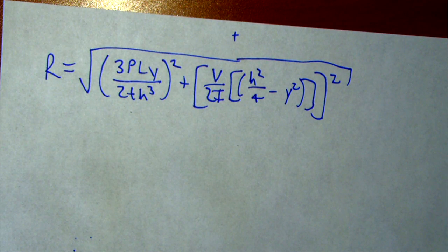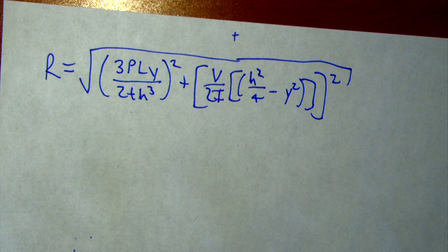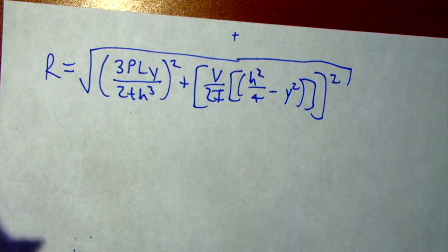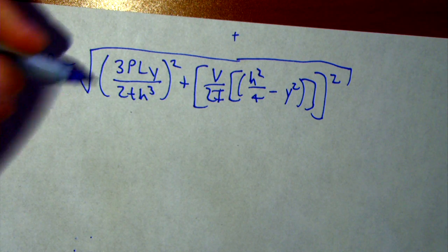So at this point you might say, what the crap, man? I thought we were going to get a Mohr circle out of this, but the value of y can change, right? So you're right. Really, you're going to get it as you might intuit, because shear stress has a different value, and the bending stress has a different value all the way along the cross section. So too, every point along the cross section is going to have a different maximum shear stress associated with it.